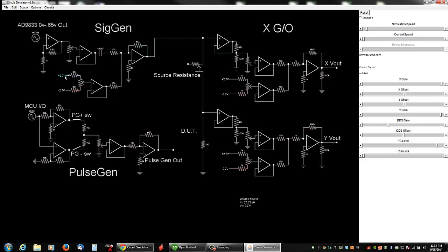On the offset, plus 2.7 volts, minus 2.7 volts. Why 2.7? Because I've already got them handy on my circuit board. Little voltage divider here, buffered, resistor again part of this gain circuit, inverting amplifier. What's the gain on that? I forget. Oh, 6.2. And the output is here.